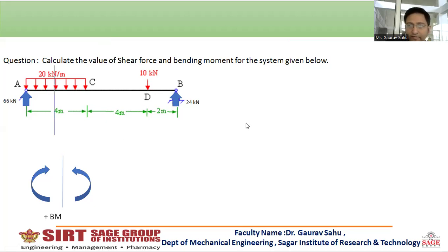So starting with creating a section, the theory of creating the section is similar to the theory of shear force, that is, between two loads, across a UDL, or between two supports, or support and load. So here a UDL will fix a point as a standard reference point, as we have done in shear force. The sections for shear force and the sections for bending moment are always the same. Whatsoever section is taken for the shear force, the same section will be followed for bending moment.